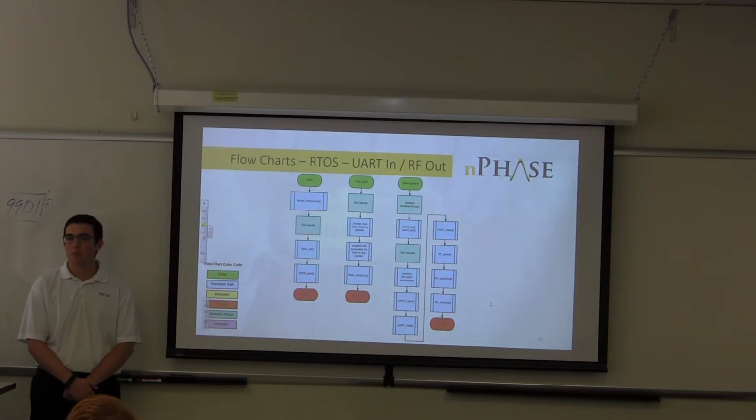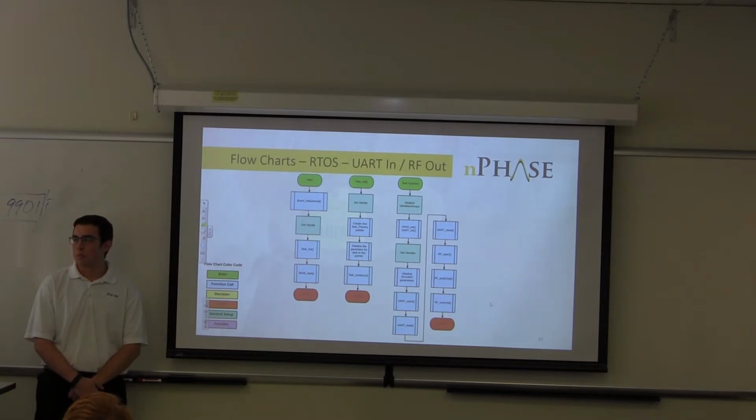So for our main, we're going to be initializing our general board initializations, as well as getting the handles and calling our task init function, and then starting those with the BIOS start. In the task init, we set the handles, create a new task param pointer, and initialize the parameters for this pointer, and then construct the task.